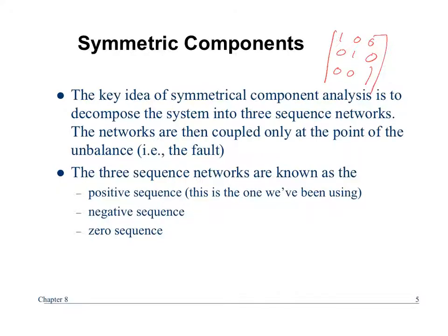So the idea of symmetrical components is to decompose those asymmetrical waveforms into symmetrical, not balanced, but symmetrical elements. We need 3 of them, because if we have 3 vectors, A, B, C, that are unbalanced, we need to break those down into 3 symmetrical ones.